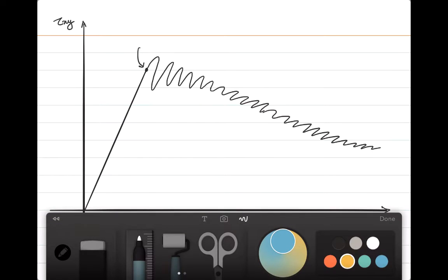In this condition, if you look carefully, you see that because the mesh is not sufficiently fine, you will have local softening of your material. You will have a sudden release of energy. So you see here that it increases, but at the same time it goes down quite large and in a very short span. And this is the snap back behavior that I was talking about, because of this softening and sudden release in energy.